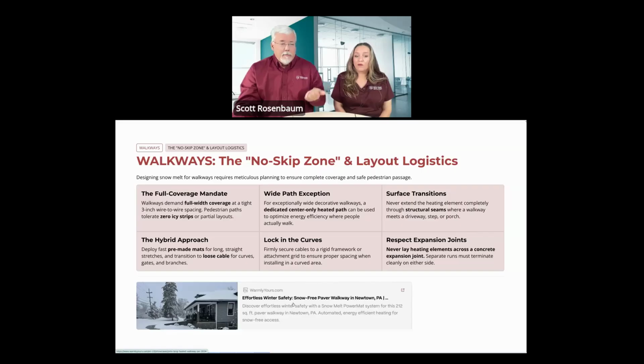And Mary can tell you that a lot of times when we talk to somebody who's never done a driveway before, their first inclination is, I'm going to heat every square inch, until they find out that they don't have enough power to heat every square inch. That's where our experts will tell you, hey, let's bring the coverage in a little bit. No one ever goes over there, so you don't need to heat that. And maybe you don't have enough power to do a whole driveway, but you can do tire tracks down the driveway, and that will reduce by 30 or 40% of your electrical load.